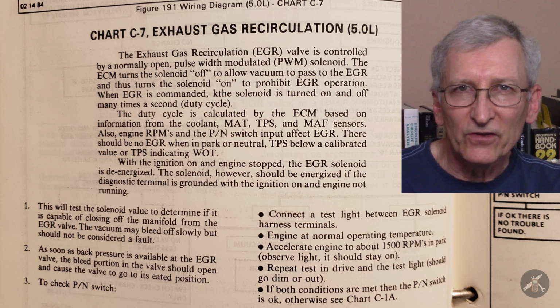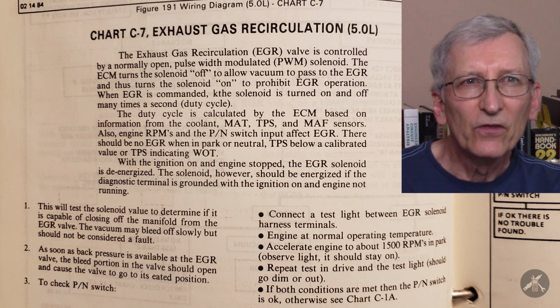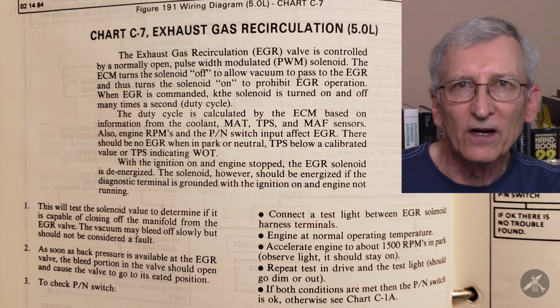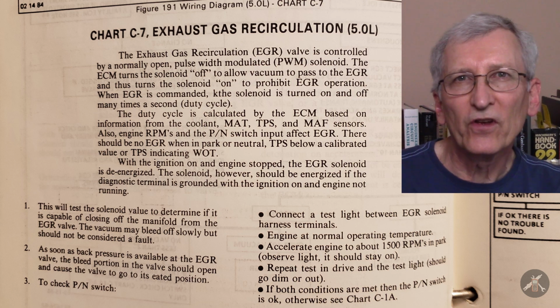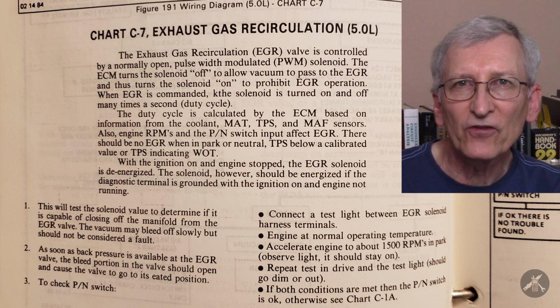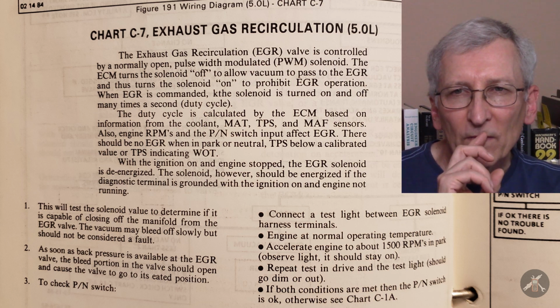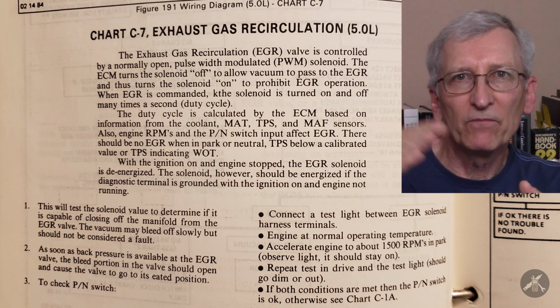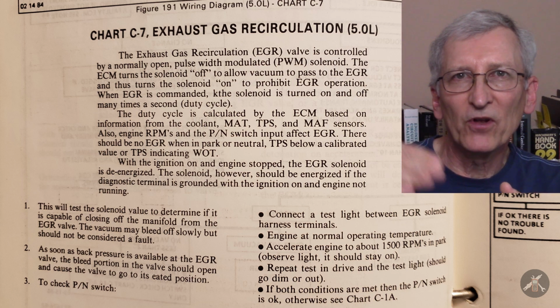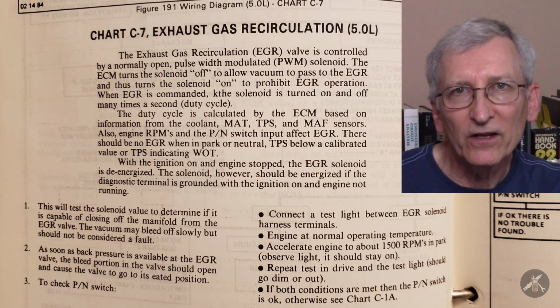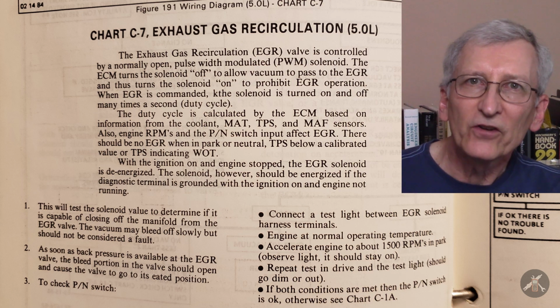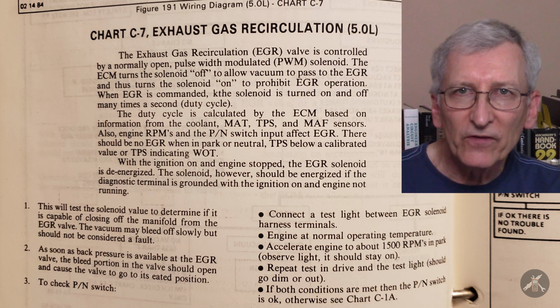The third level in the EGR circuit is what they call a negative back pressure valve on these cars, and that is when it senses negative pulsations in the exhaust system, the valve will vent and close. And so if you're at low speed, the throttle's not open, and the exhaust manifolds always have pulsations in them. And when those pulsations go negative, they will vent the valve. So it's really hard to understand how much the valve is open.